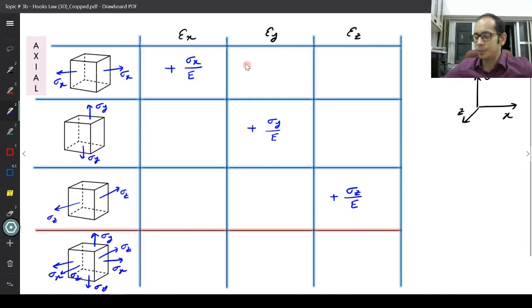Let's come over here, right? Go back to Poisson's ratio. What did we just discuss in that Poisson's ratio? Remember that bar which had the force or the stress along the x direction; along the other two directions, my epsilon y was what? My epsilon y was negative of nu epsilon x.